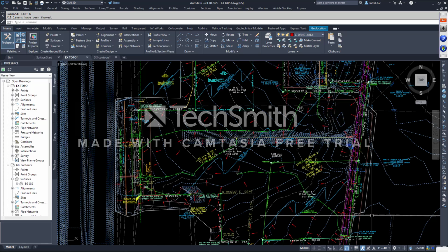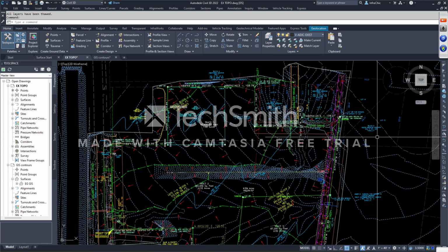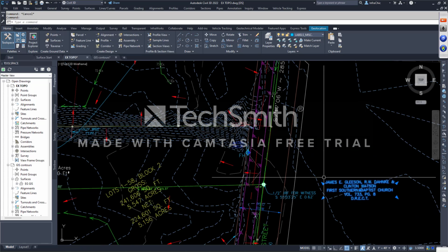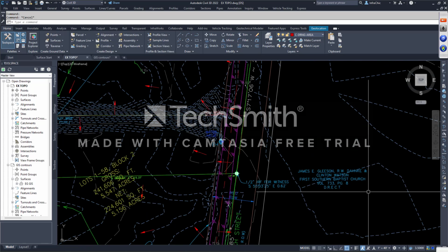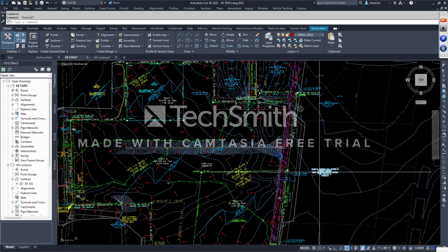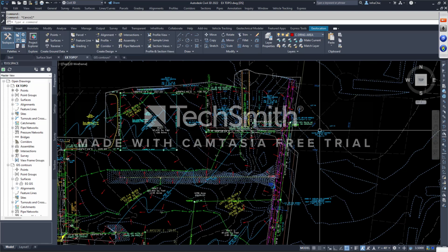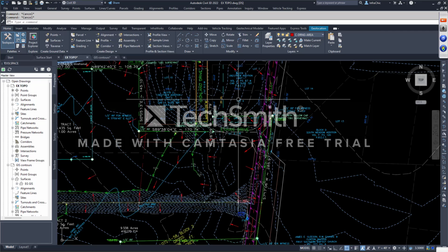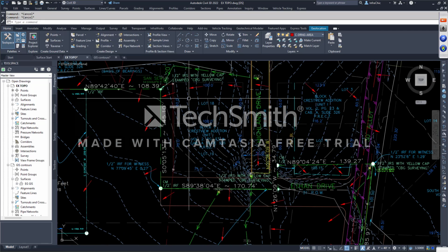I got the adjoiner line work. All surveyors must give us adjoining line work. I need to know in the adjoiners who owns them, who owns each lot over here, what the lot number is, what block it might be part of. I need to know the bearings and the eastings. Is it lot number 4, 5? Don't necessarily need to have distances on existing adjoiners. That's never been asked for. They do want street names and right-of-ways, though.